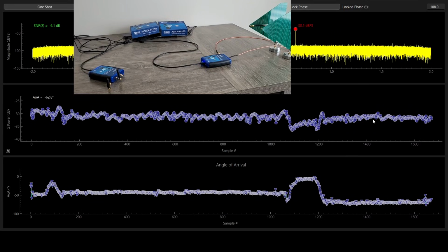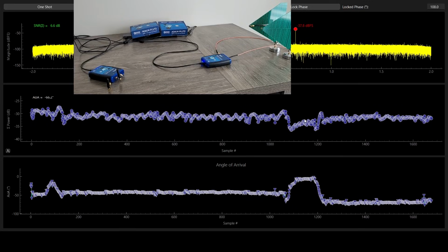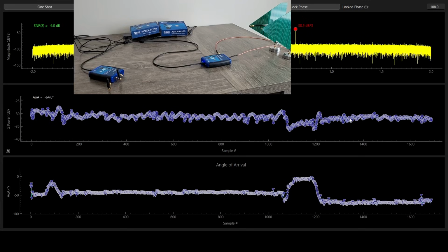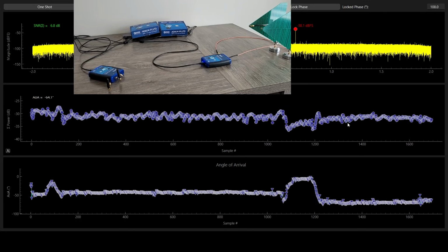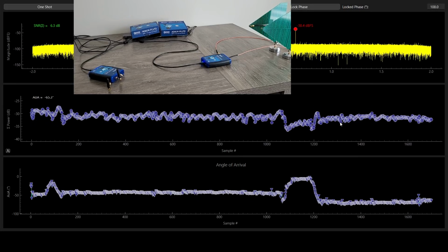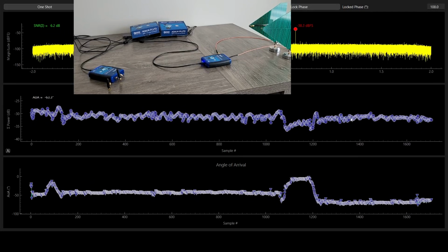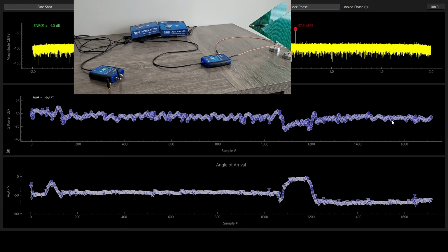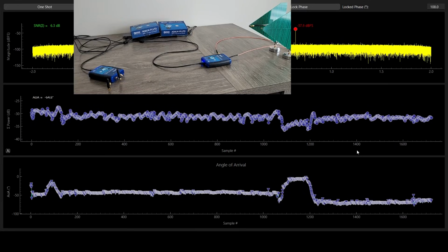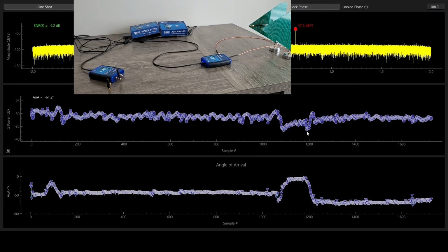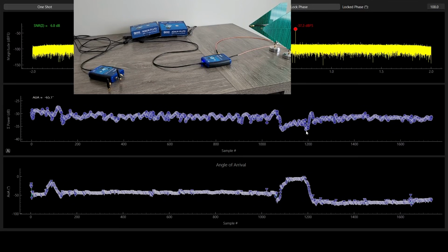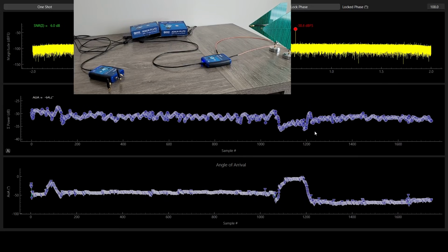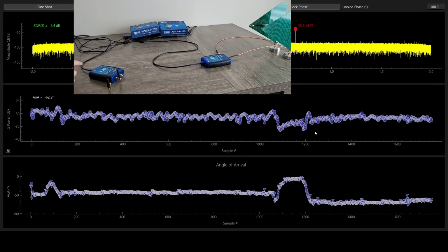But still, this seems to be somewhat reasonable alignment happening here. Although we are changing the RX angle, we still can keep up with the beam after some amount of time. But after some time, as the phase difference becomes too much so that we cannot find the difference and correct it, we just start losing the power tracking.